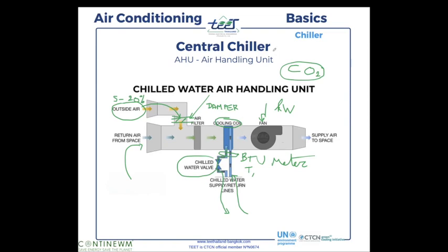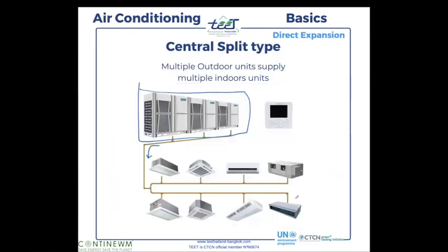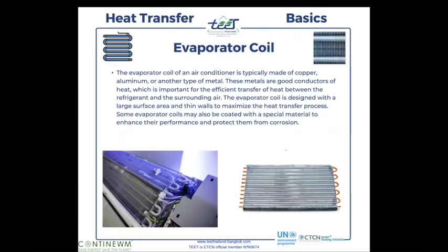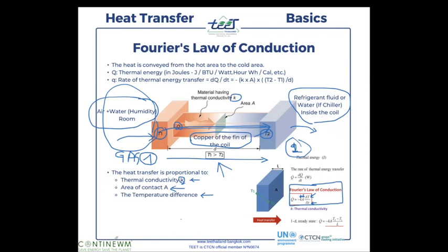There was a question I think I read in the chat, sorry I missed that, about where to install the BTU meter. So basically, you install it here. The BTU meter, you install it on the water pipe that brings the water from the chiller to the cooling coil of the AHU, and on the water pipe that takes the water back to the chiller. Because the BTU meter, if you remember this slide, is very important in many aspects, and will answer this question.